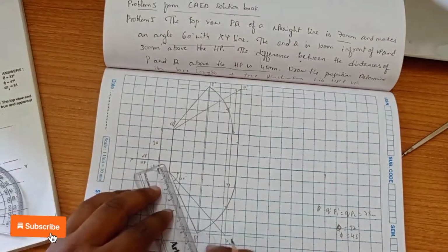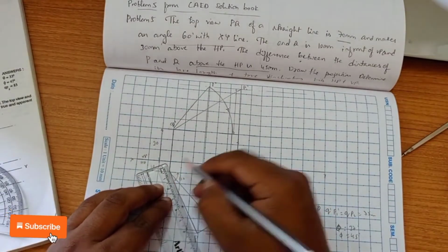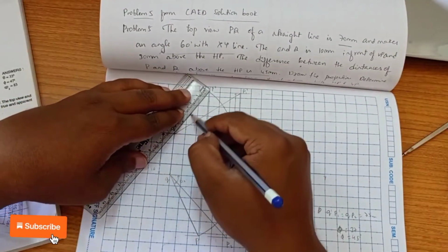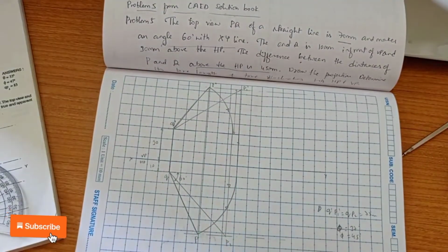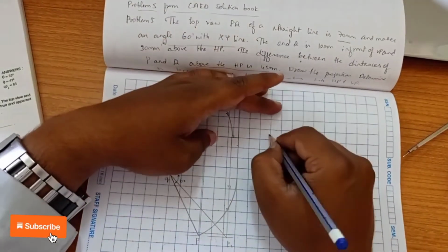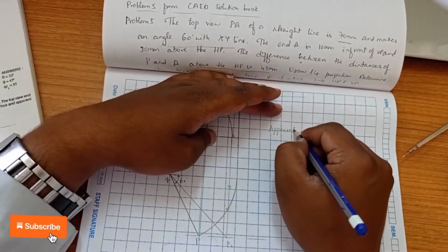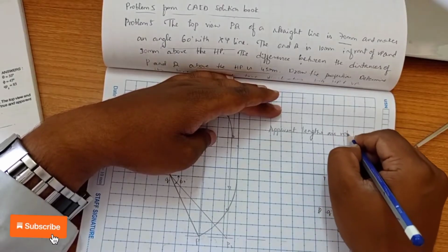So remember it. Always apparent lengths are going to be rotated. Okay. So I'm going to make this apparent length darker. Okay. So apparent lengths are always rotated. True lengths are never rotated. Okay. So remember it. This is one of the important points. So apparent lengths are rotated